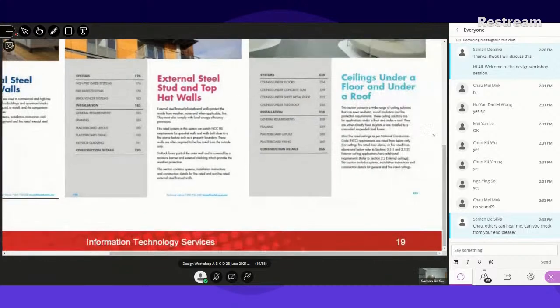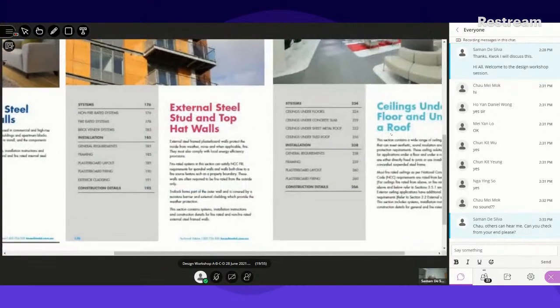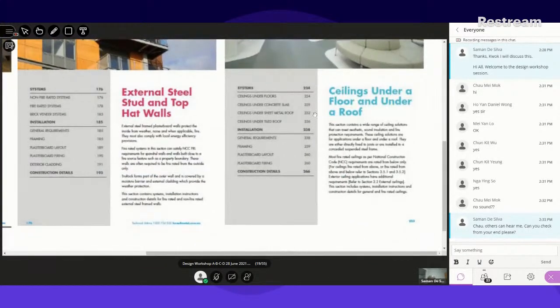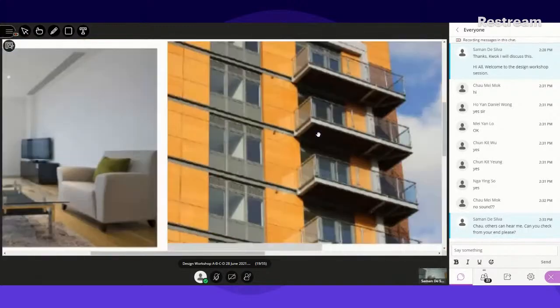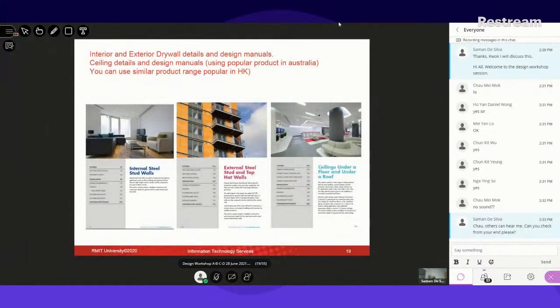In most of the designs I see, students draw a straight line from concrete wall to concrete wall, thinking that it is a plastered, very smooth surface. No, it is not. It can rather be covered by stud walls or drywall methods.